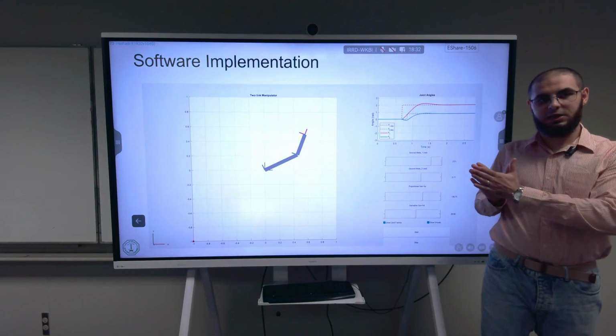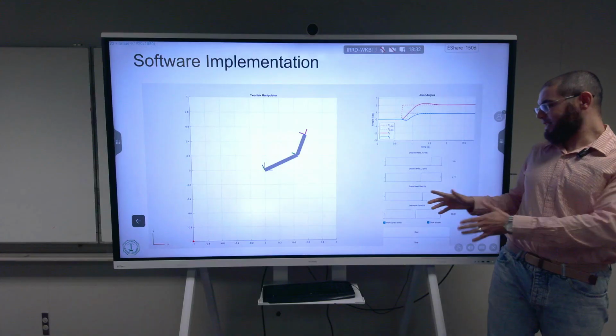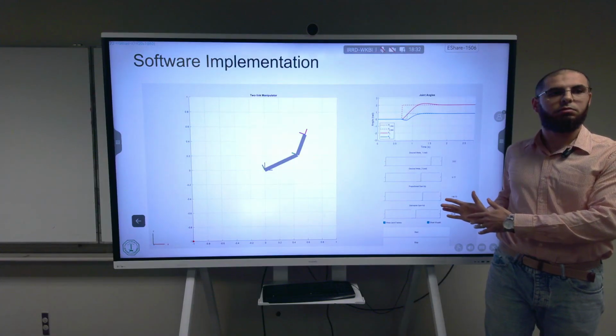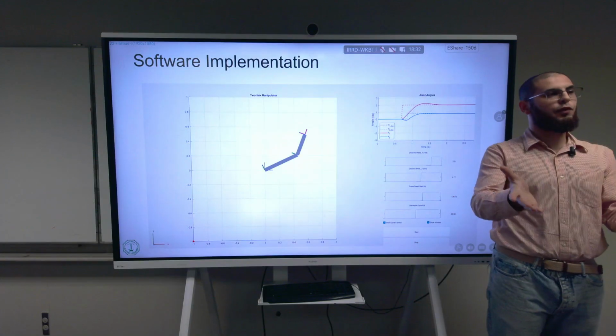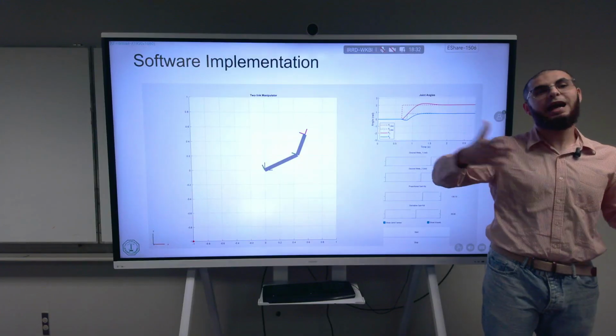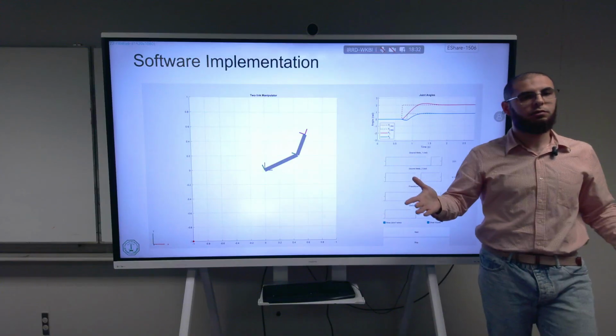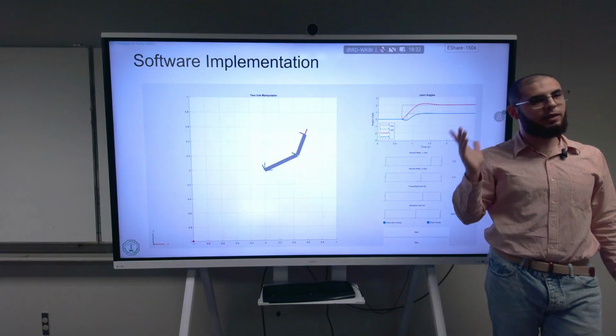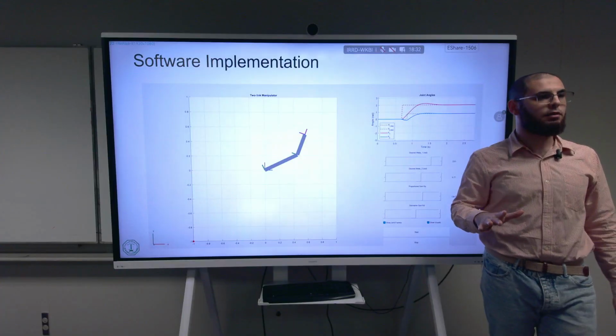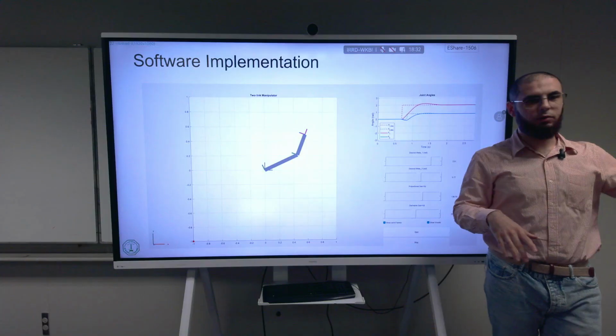And there's something I haven't discussed here, which is, why not choose the gains to be the highest possible? The control effort will be problematic, right? I'm going to get high control effort, right? What's the problem of high control effort? Saturation. There's even a worse problem that, again, people rarely look at. Power consumption.